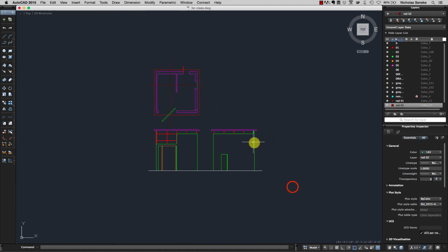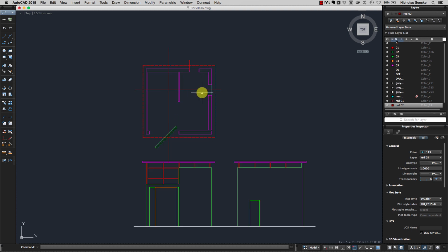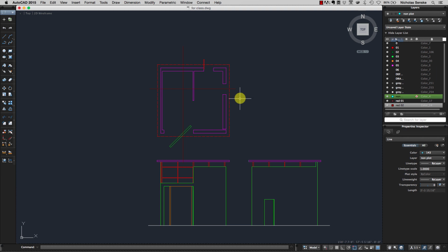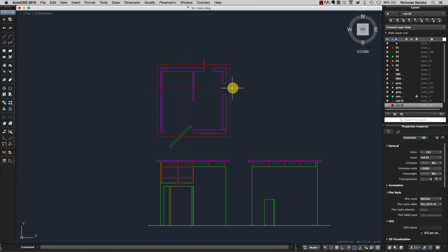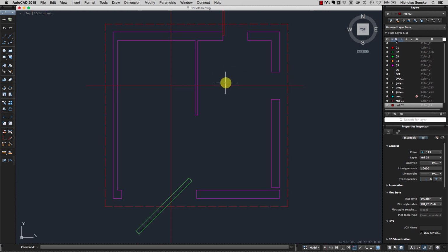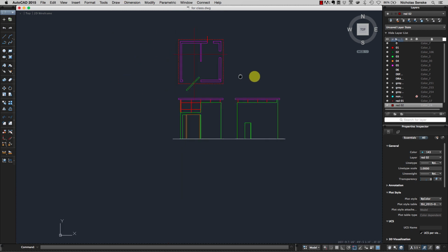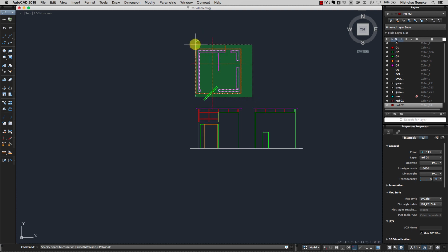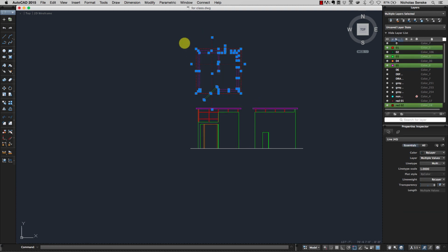There we go. Okay, so I got my plan here, and to draw a section, you want to project up from the section line anything that it touches, right? That's the stuff that it cut, and that's going to get projected up to start the section. And then from that you're going to take the lines from the elevations, and then you're going to use those to generate the horizontal. So this is kind of similar to the process of creating elevations from the last assignment.